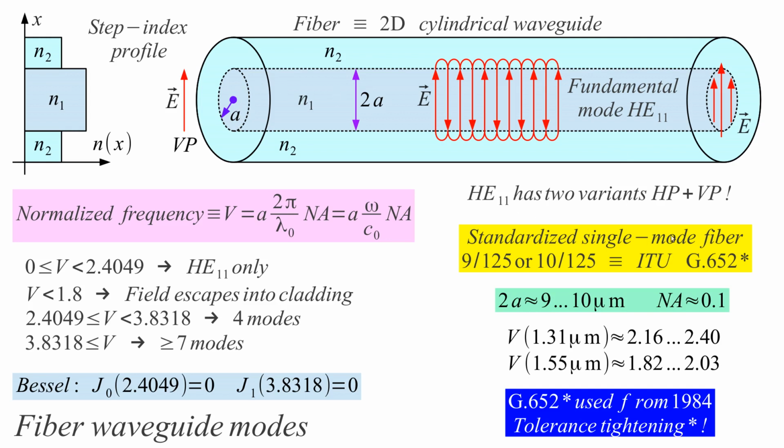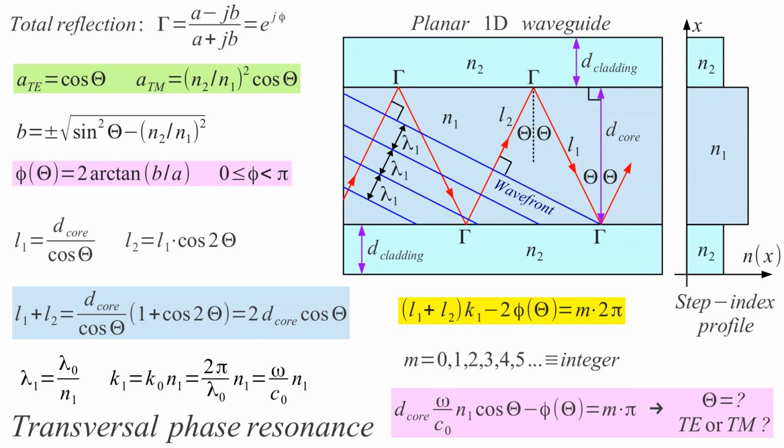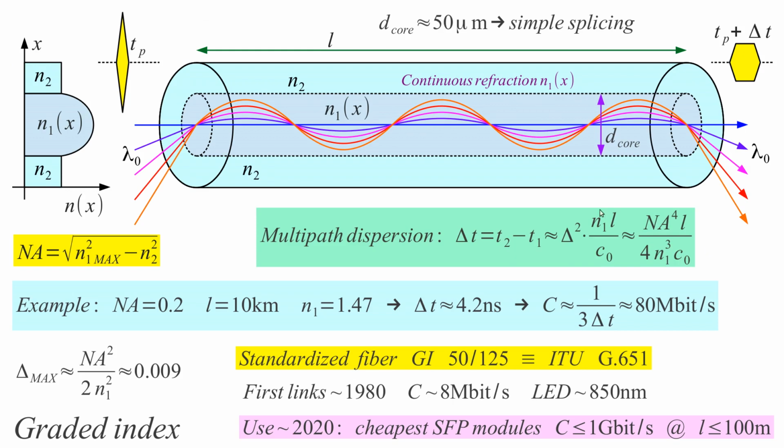So the single mode fiber was actually well known. The theory was well known, but in practice, fibers with much wider, much thicker cores had to be used because of the connection accuracy. So this was really a mechanical constraint, not an electrical constraint. Equations were known.